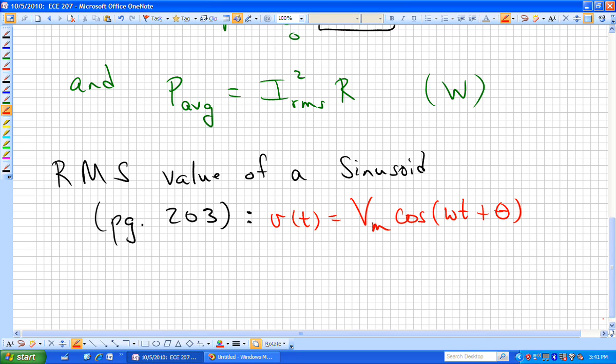Theta is typically in degrees. Omega has units of radians per second. How many radians in a revolution? 2 pi. So 2 pi is equivalent to 360 degrees. You probably need that relationship to convert the units either from radians to degrees or degrees to radians, so that if you needed to compute that, to take the cosine, you don't want to be mixing radians and degrees.